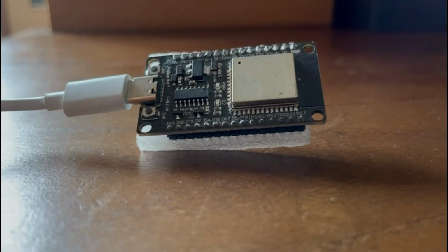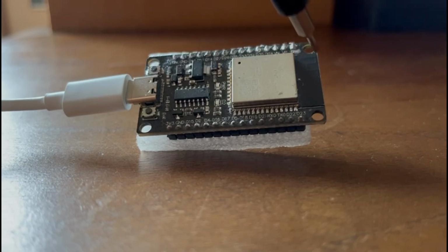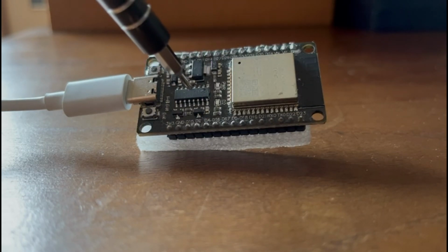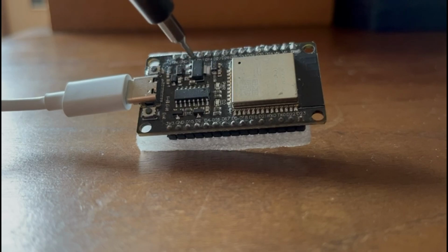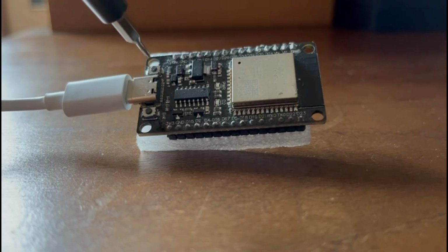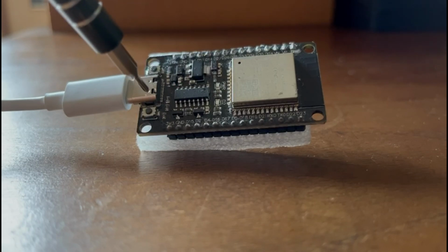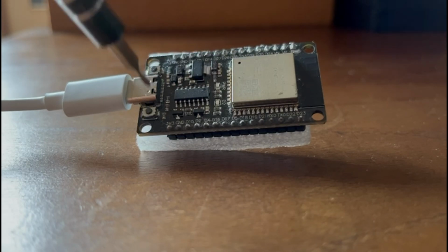This is the board that we are going to use today. The microcontroller itself, the ESP32, is here on this module, fully covered in metal to try to reduce the amount of noise that reaches the most sensitive part of the system, that is the transceiver. The transceiver is then connected to here, this small antenna that works at 2.4 GHz. Then here on the left, we got our serial to USB chip. On the top, our power supply, the USB connector that provides not only data but also power, and then two buttons. The one on top is a reset button, and then the one on the bottom can be user-defined. And this is the button that we are going to use to mute and unmute our microphone.